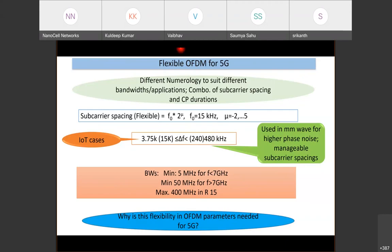What are we making flexible in that OFDM technology? We are making what is called the subcarrier spacing, which is a very fundamental parameter in OFDM. Instead of a fixed value, which was the case in LTE, because remember LTE was primarily geared for mobile broadband, now we are in different zones.